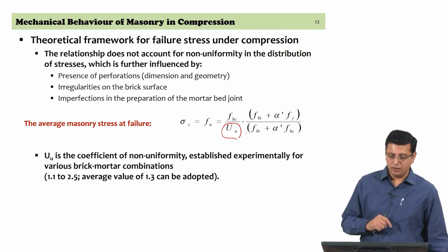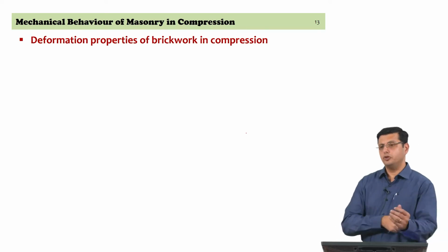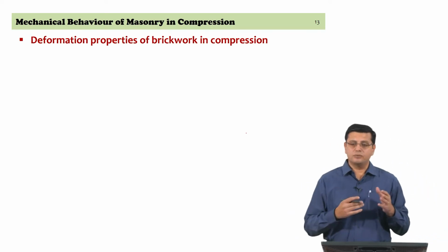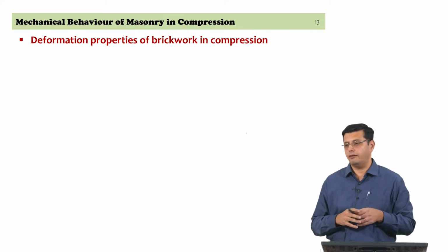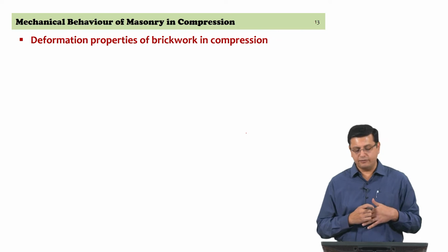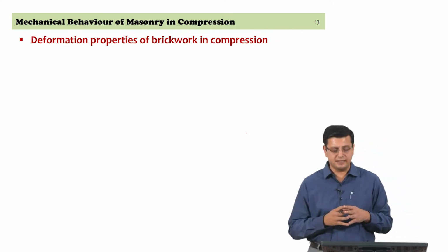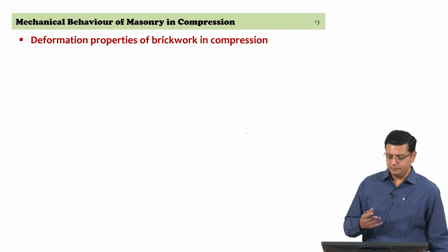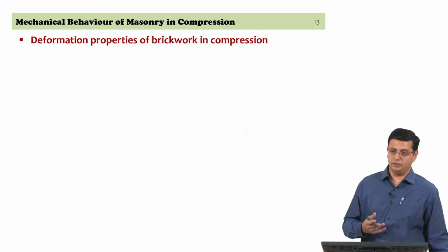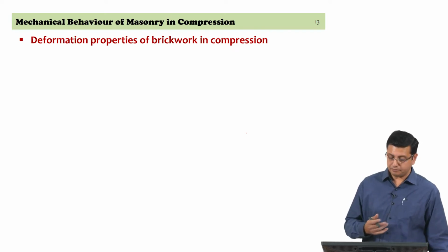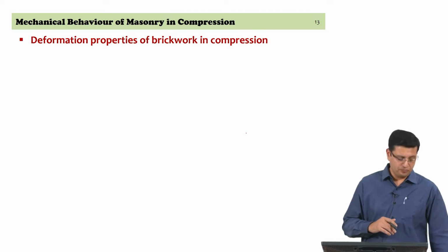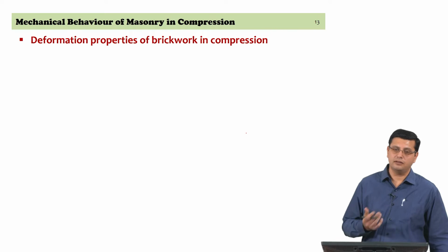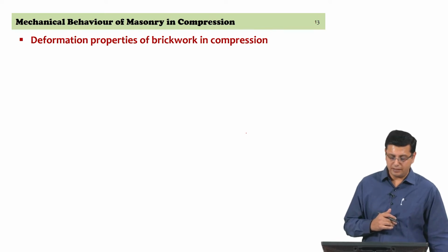Okay. So, continuing, it is useful to look at, in terms of stress strain curves, what sort of an analytical formulation fits the stress strain curve of masonry itself. Again, we are examining compression, and in a way it is not very different from concrete in its behavior in compression, and studies were carried out a few decades ago, and they are still valid because they do a rather good job in capturing the stress strain behavior of masonry in compression.